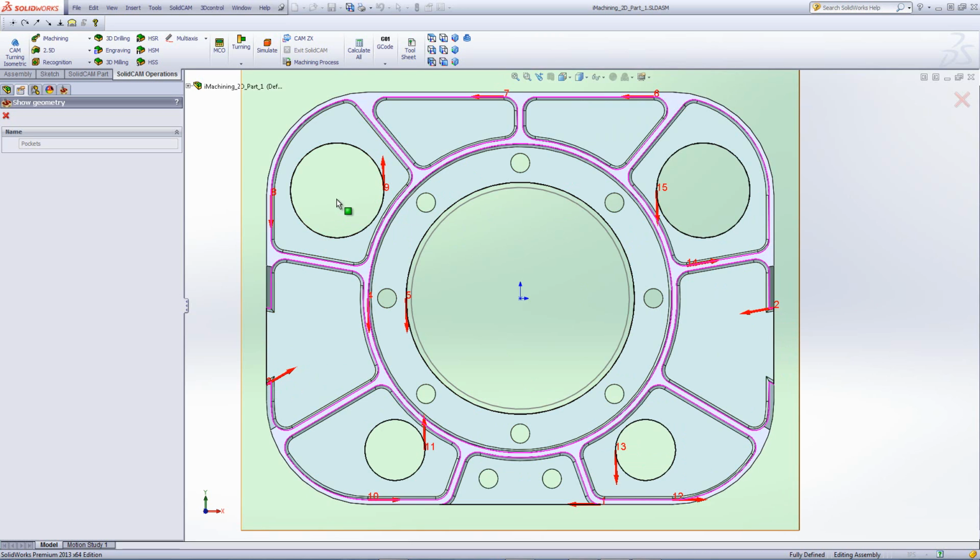These areas where we cleared before with the iMachining are marked with 2 chains, an outside chain and an inside chain, where the inside chain is marked as open, knowing that it can also come in from the outside over here. And the same with all of these chains over there. The rest are marked as regular closed pockets.